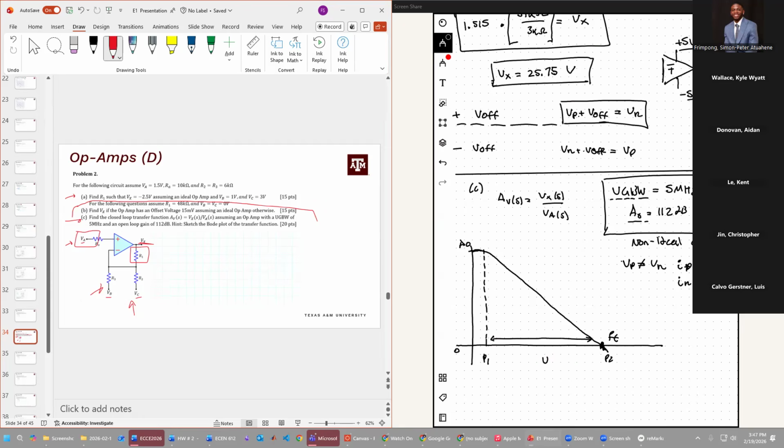This is like the base characterization of the op amp, like the pure frequency response. And oftentimes we are just operating on a portion of this curve whenever we're using the op amp. And you know, the higher gain that you want, the lower your bandwidth, right?